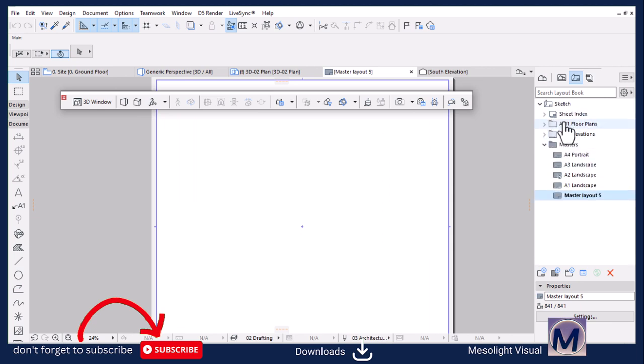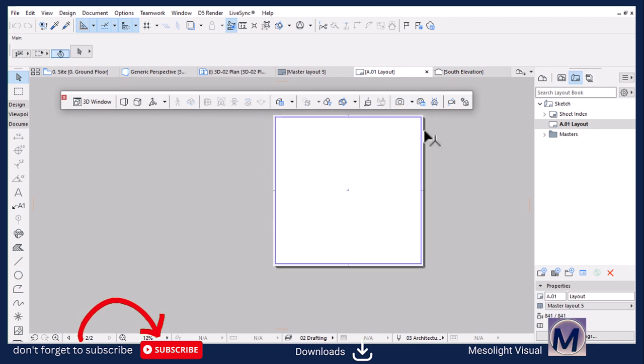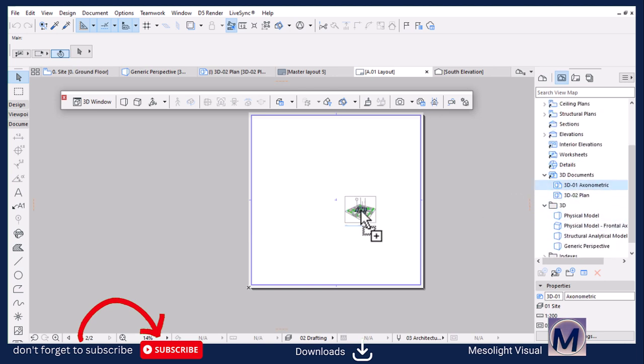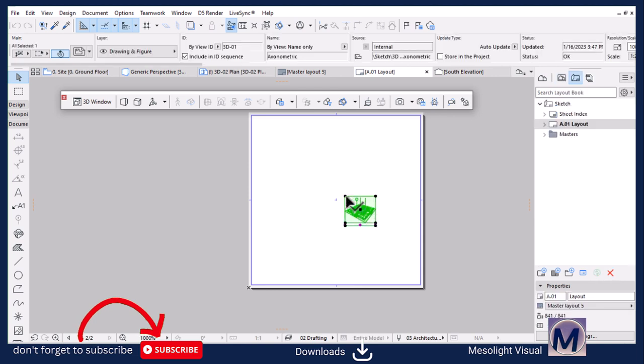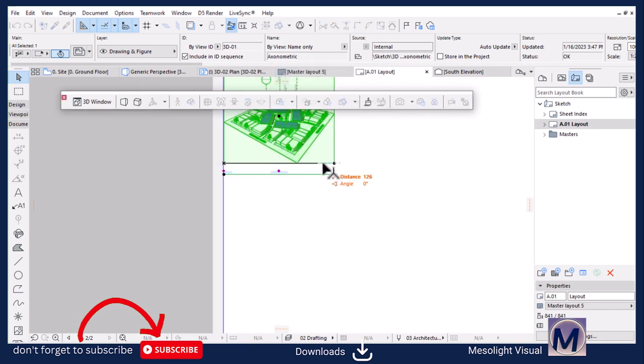Let me delete all these layouts and create our own layout. Let's use the master we just created. Perfect. And then we can now assign or throw in our elements, our drawings. Let's move it from the point to the corner there, and then I'll hit Control K and then hit OK to rescale this.